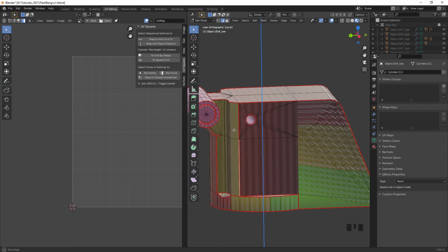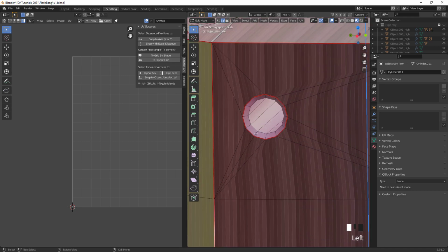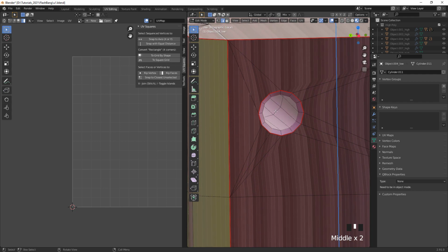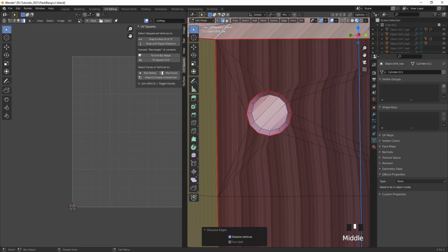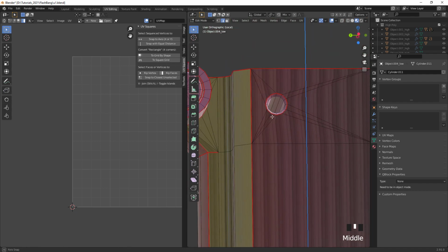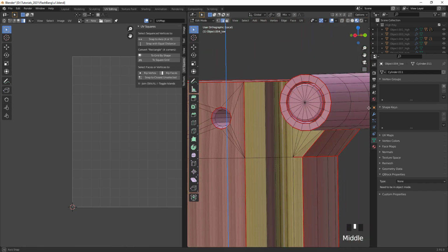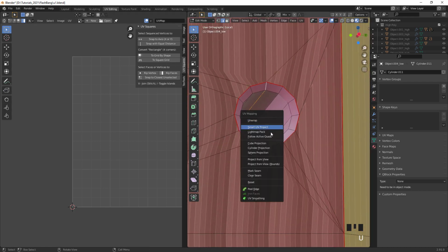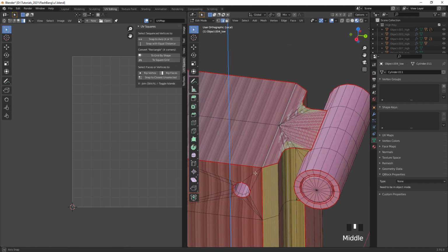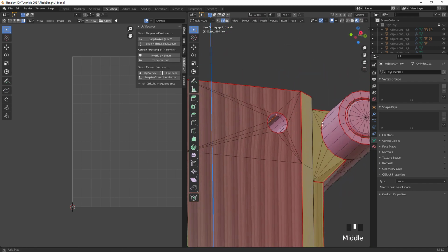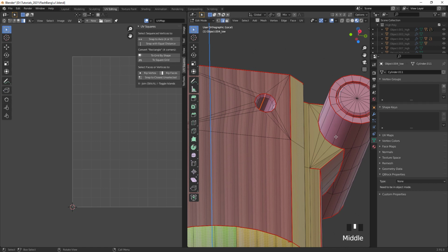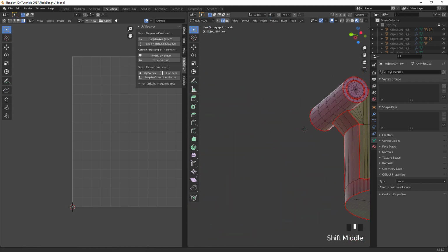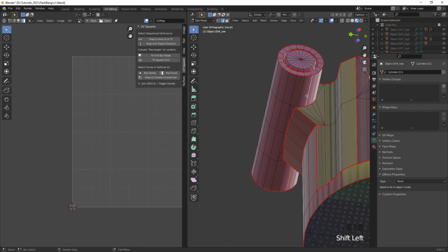I think I'm gonna leave this one here, but then I'm gonna have a seam going through here. And we can actually dissolve this edge there in the center first. That only adds to our poly count. And let me just select it here from the top. These edges I'm gonna mark as seam. And that way we can also unwrap that as a stripe. Now let's take a look here where we also have to define an edge seam on both sides. Mark it.